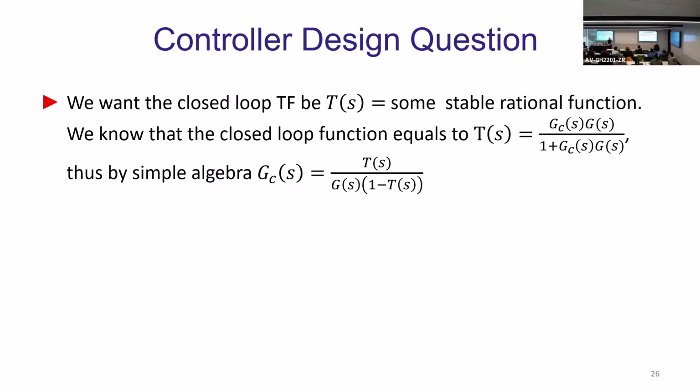Design doesn't finish when you get all your parameters together. You have to test your design. I mean, here is the testing of the design. Closed loop transfer function will be that same. When you design G of C using that formula, T of S will be that same, right? So it will be closed loop, and it will be your desired transfer function in closed loop, right? Because you, in the first place, designed it to be that. So obviously it satisfies all of the design criteria because you designed it in the first place, right? You started with it. It will have all of the characteristics that you love to see your system in closed loop.